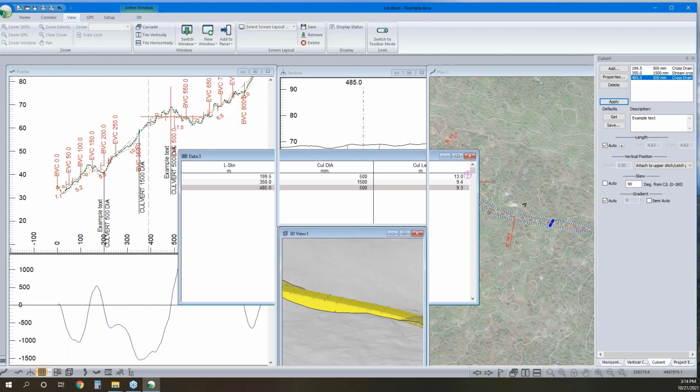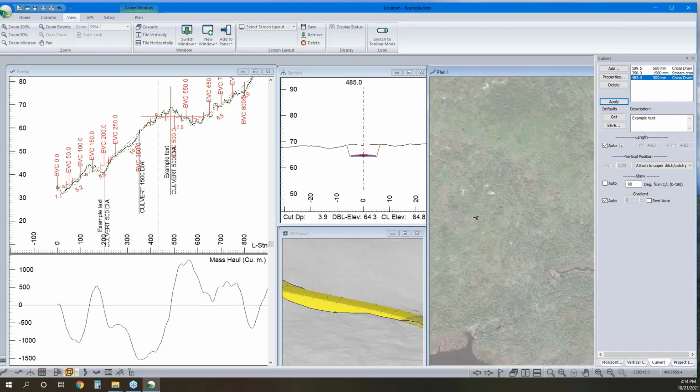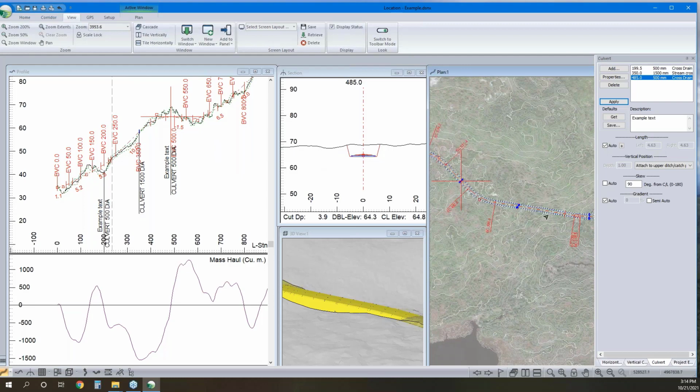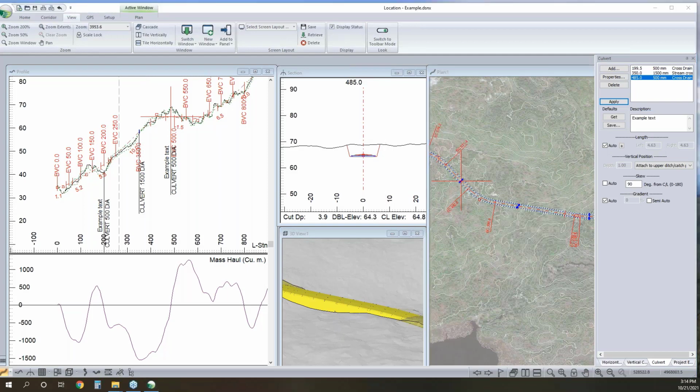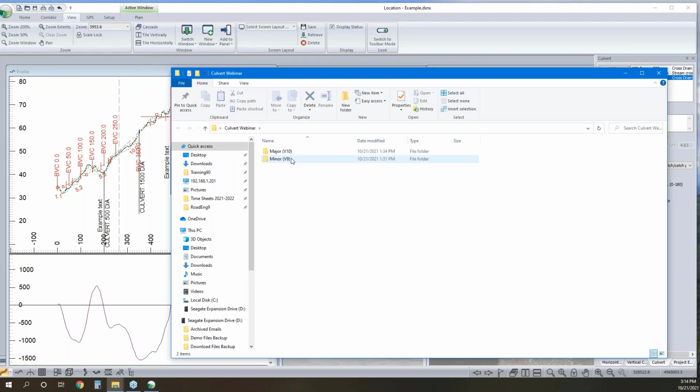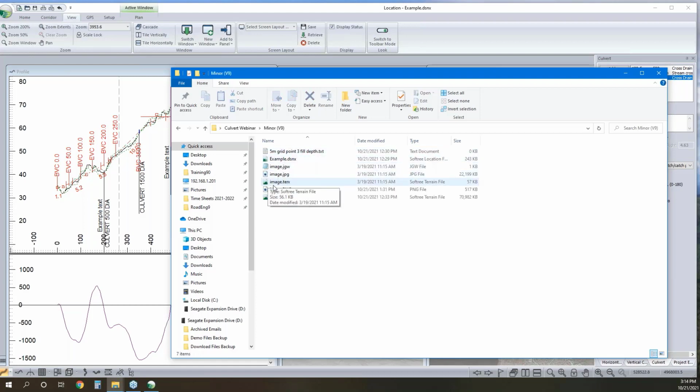Now, this example that I have here, I probably wouldn't require as many pipes as what I've clicked in, because when I clicked in this alignment, I used another feature in terrain. So I've used our Watersheds feature to choose my alignment, so I can go put my road on the high spots, reduce how much natural flow I divert, and also reduce the number of culverts I need.